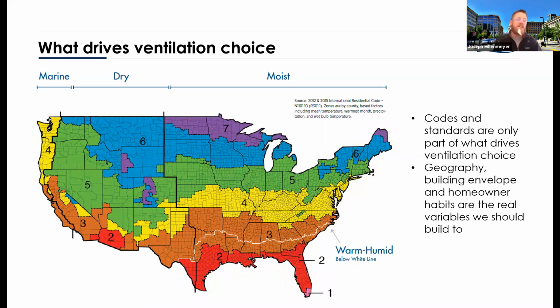The other nice thing about steam, and we talked about people being used to the climate conditions that they live in. It's kind of a hard sell, but if you're out in the arid West, you should be humidifying during the warm months. I mean, dry air is dry air regardless of the temperature that surrounds it. And as I said, it's kind of one of those situations where I think, to an extent, people in those areas have kind of gotten used to it.